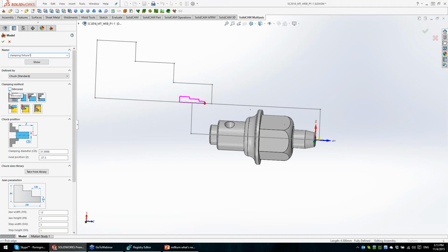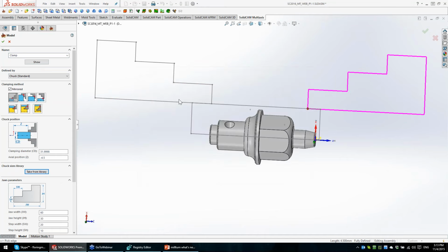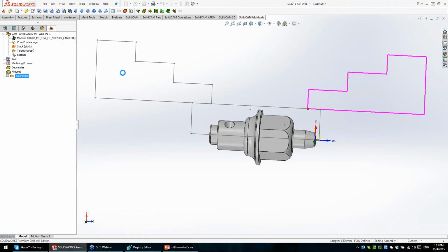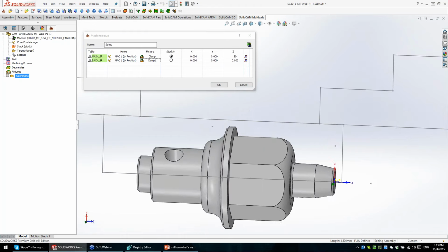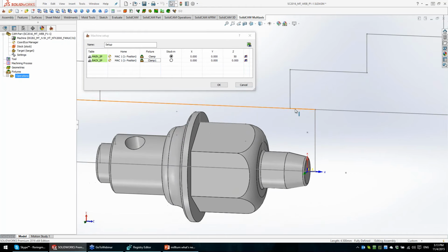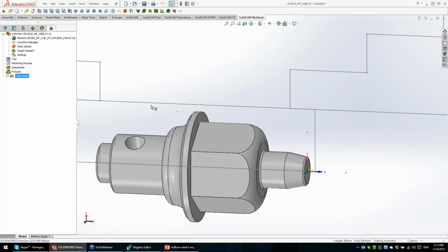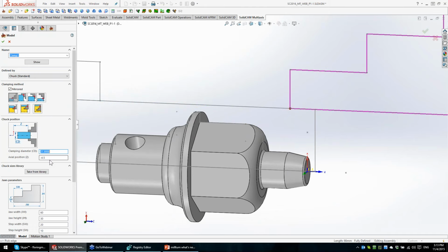Number 1, and it's a mirrored version. Take from the library and generate also the envelope. Okay, here I did a mistake. I don't want, when I am on the back spindle, to catch the part on the stock, because here it will be already machined. So let's go and fix this mistake.